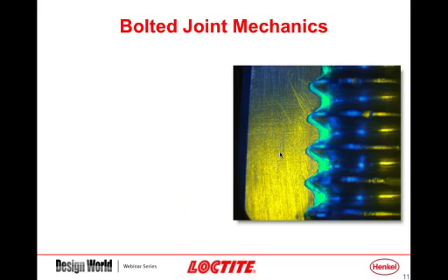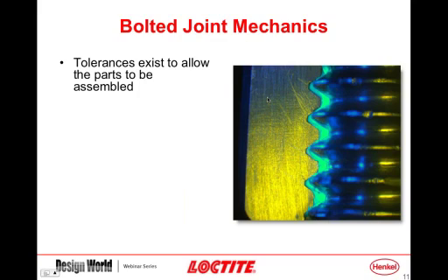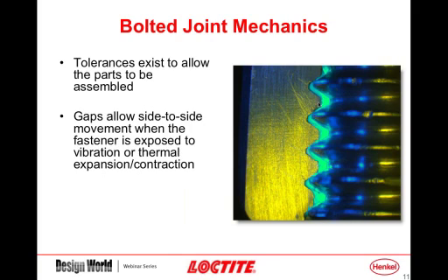And what I chose this photo for is that it's very representative of what you've got. You've got a gap that's required in the thread root, and you need that obviously so that you can move the nut over the bolt and tighten it up. These gaps, though, come to the root cause of the performance that you get out of a fastener, and also how you can get a failure out of a fastener.